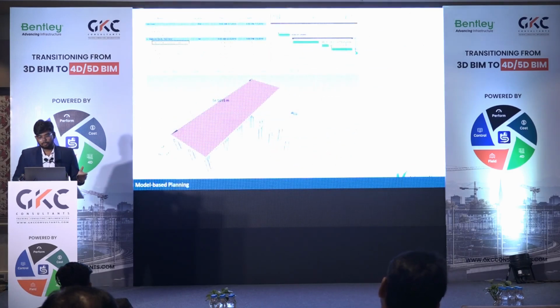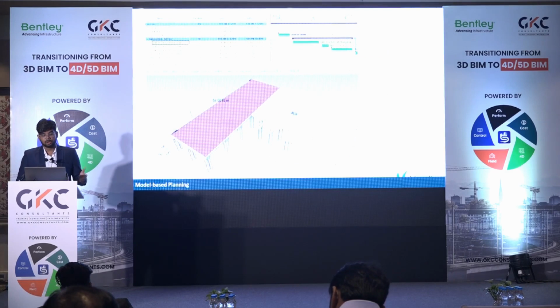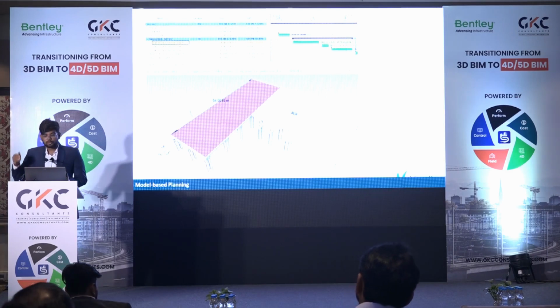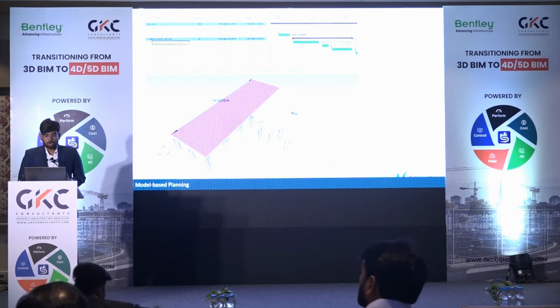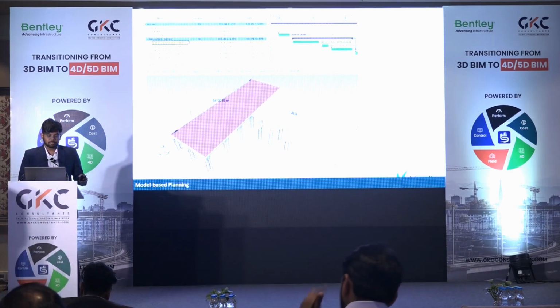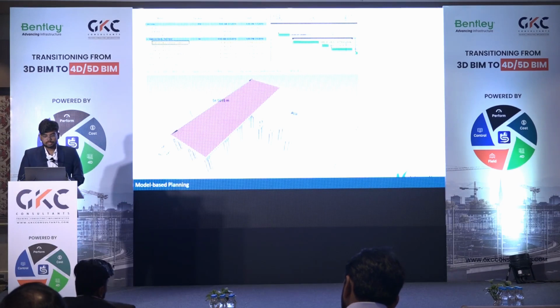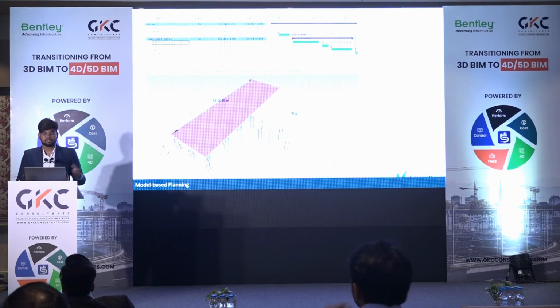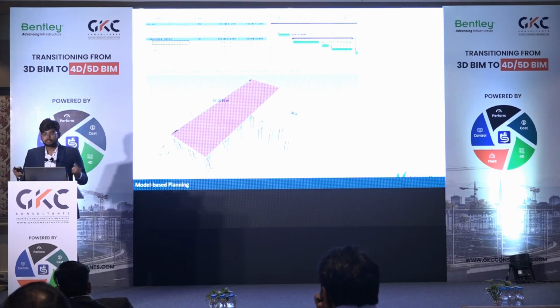This is a slab from the design model which is 54 meters long. And here we just have one task that has been previously planned. Now you tell me whether we are ever going to construct a slab that long in a single stretch. It doesn't communicate how this slab is going to be constructed, from which part the construction is going to take place, or where the equipment is going to stay during this construction. Just imagine the bottom part is missing, and you take this bar chart to the people on the construction site, and they would not know how to do it, and they would have to decide there while planning.